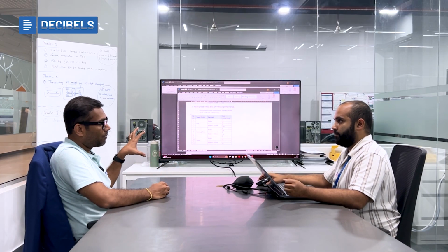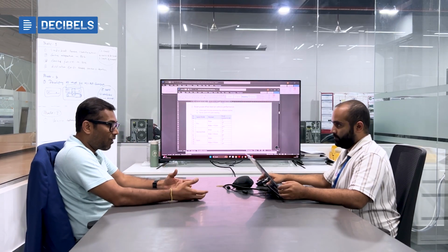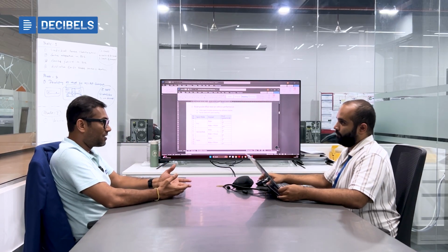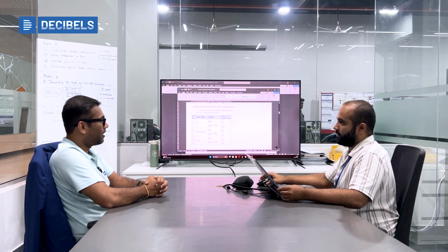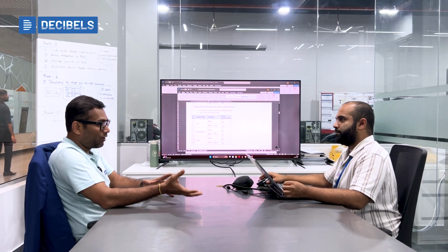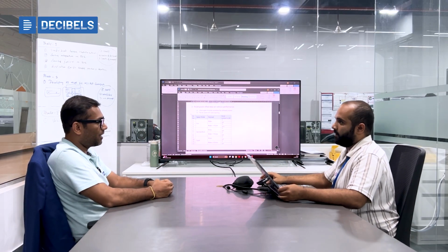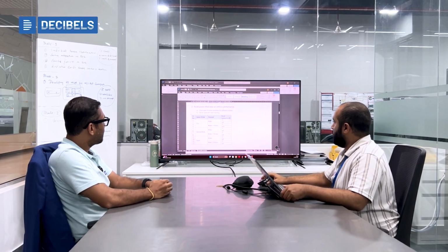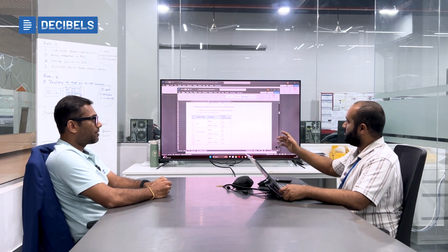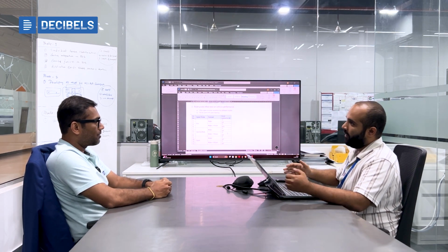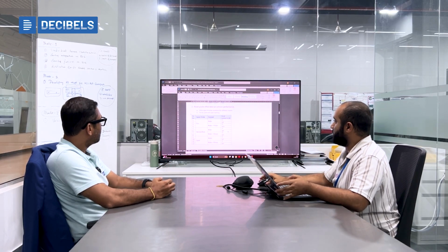Also, from the vehicle perspective, we want to study how much current is being drawn, how much power the motor is using, how much torque the motor is able to produce, and so on. The dyno will measure wheel torque, and then we can use the gear ratios to interpret the motor torque and other things. Right, exactly. I do have one small report that I've done before. I'll run you through the different experiments, then we can go on to the report and discuss the results that we've got.